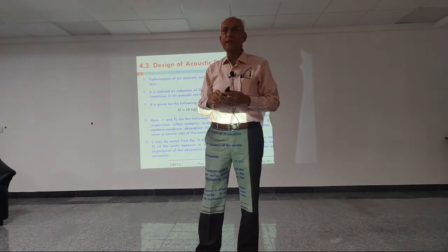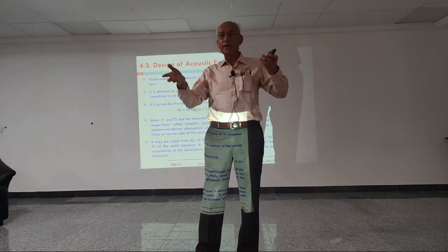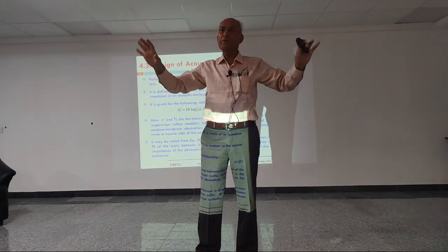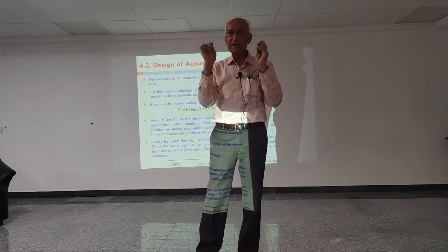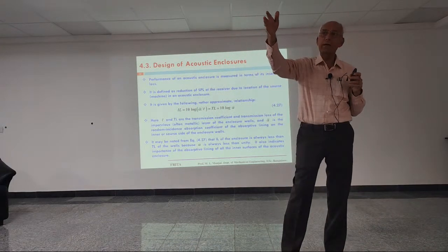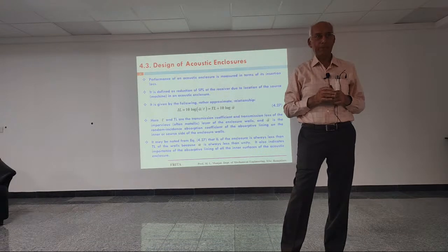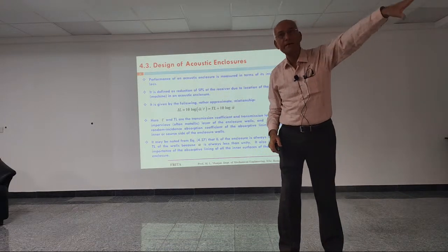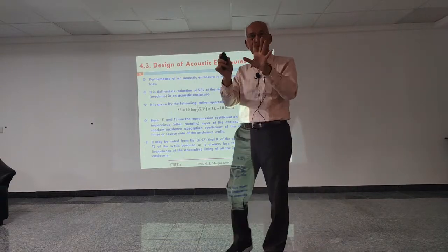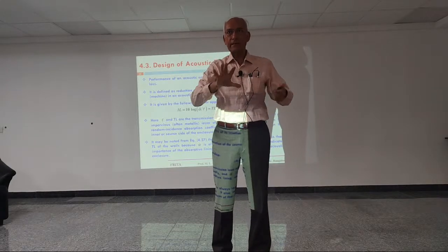So in this way, we assess the impact of the factory, what it would be if we don't do anything. Then we start with the next step. If I put this wall with a noise reduction of minimum 20 decibel, then what will happen? Or on this side, I do only 15 decibel, because we don't want to overspend. The idea is to do what is just necessary. So we put those reductions and then recalculated.